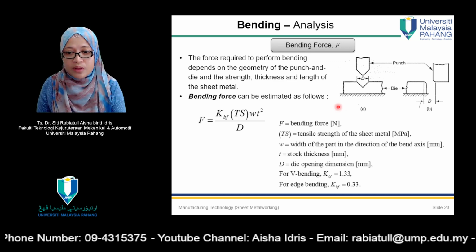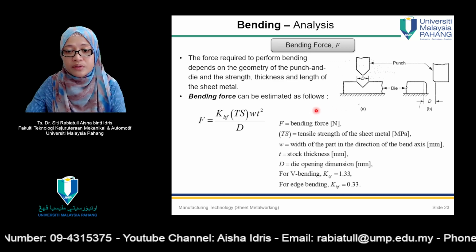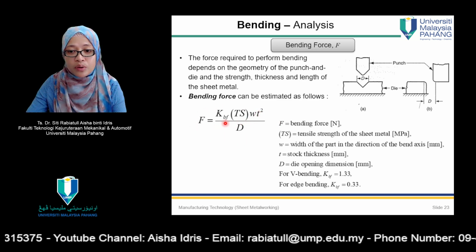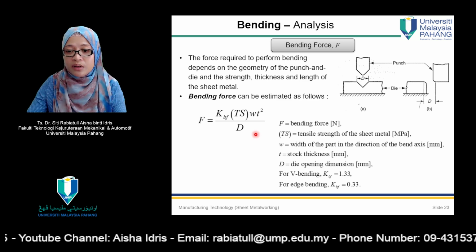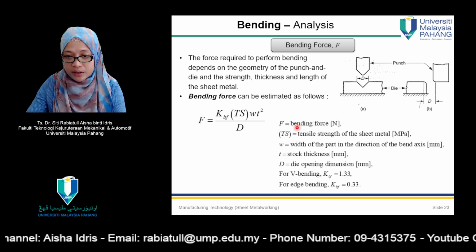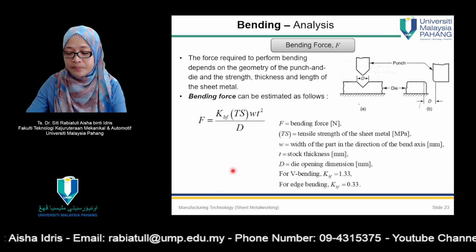And this is the formula for bending force. F equals KBF times TS times W times T squared divided by D. And you may look at the terminology over here for each of the symbols there.